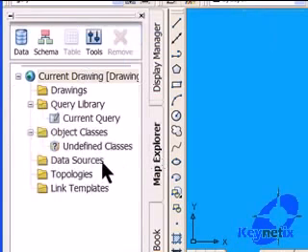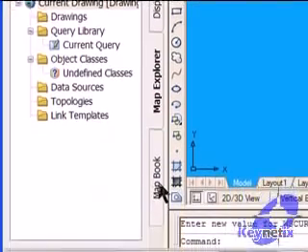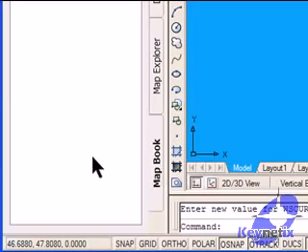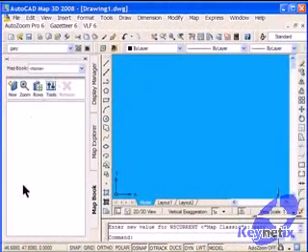The Map Explorer, which is used more for traditional CAD data, bringing the CAD data in from other drawings, analysing it, linking it out to databases, etc. And map books, i.e. when you want to plot out a whole series of plots for an area over and over again, generating a map book can save an awful lot of time. So this is your task pane.